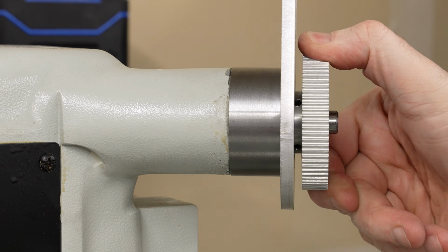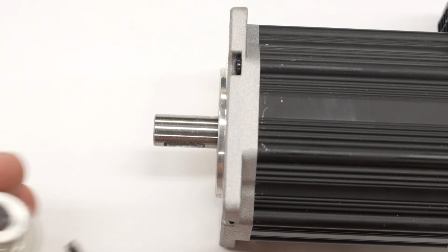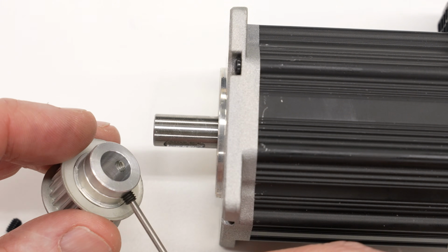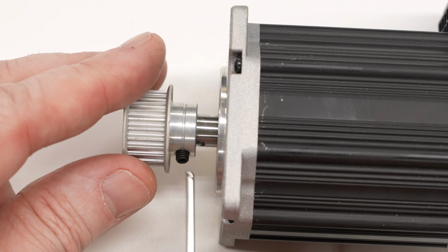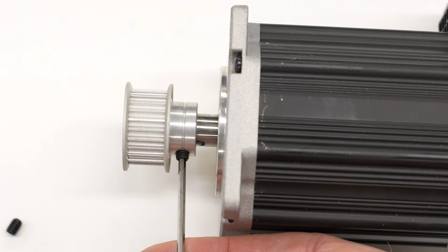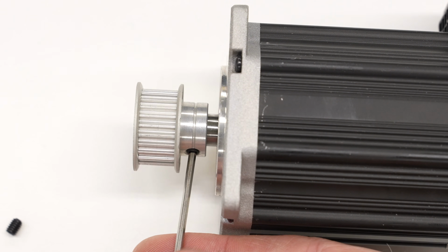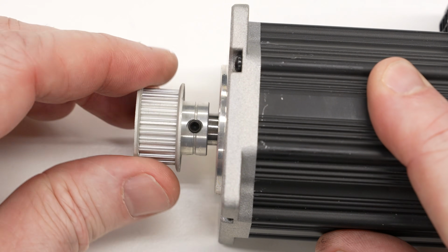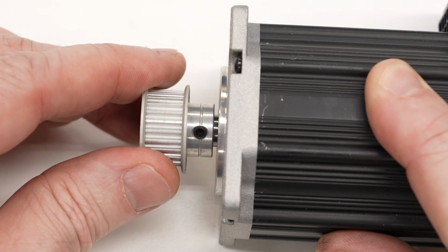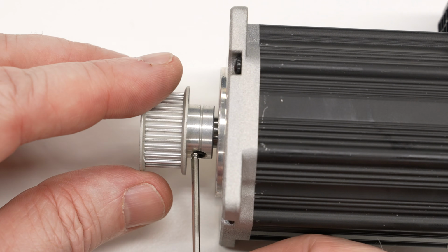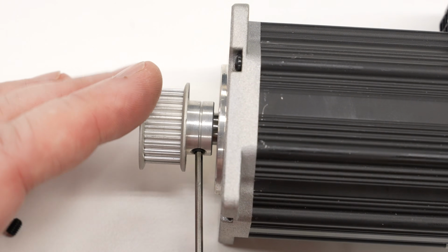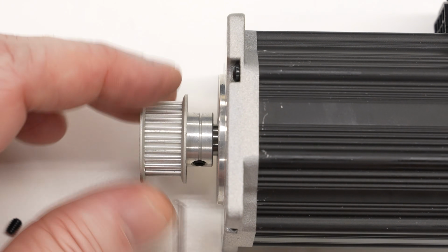And that looks great. And just like with the Z motor, I've bored out the small pulley to fit over the shaft, and I've got a dog point set screw that I'll put into the keyway. The usual caveats and disclaimers apply. It's probably not the best way to do it, but it's the way I chose to do it. And I've got the CAD model set up so that the pulley should be located with that dog point set screw all the way at the bottom of the keyway.